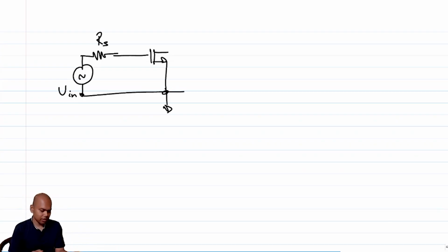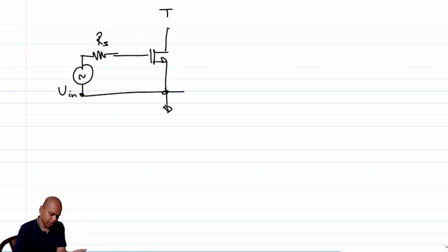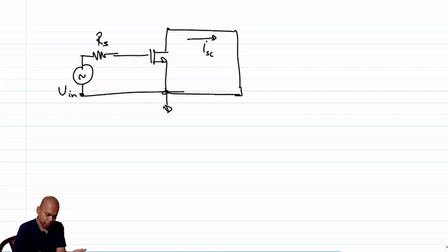One of the primary reasons is, as you must remember, we had made our changes in such a way that instead of using a load resistance, we used an inductor to get rid of the headroom problem. And the good thing about the inductor is that an ideal inductor does not have any R, which means it does not contribute to noise, right? So if it doesn't contribute to noise and gives higher impedance, I do not have to bother about it. I'll just let it be, and for the purpose of this lecture, I'll be interested in only the short circuit output current.